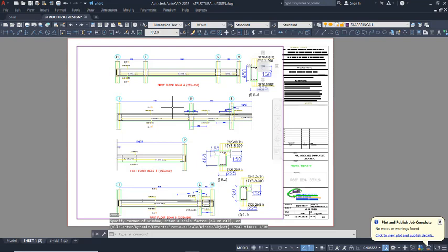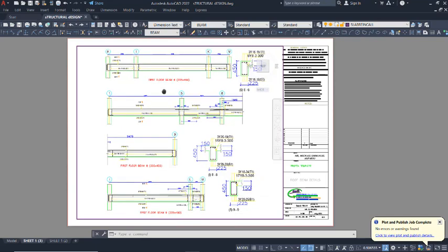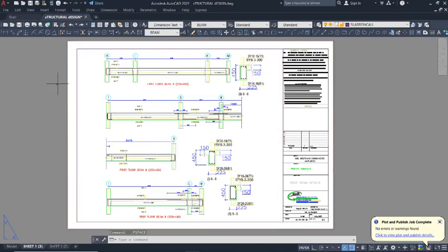You can see how the drawing has fit into the title block. At this point, if you are okay with this scale, you don't need to use the wheel of the mouse to scroll. Just press the wheel of the mouse to pan, so as to position the drawing properly, just like this. After having positioned this drawing, you know that you are now plotting it to scale 1:30 successfully. So this is okay. Now you just have to double click outside.